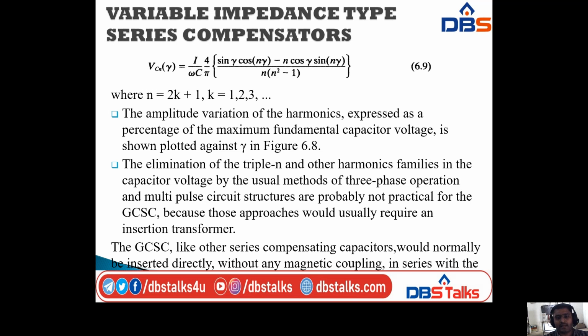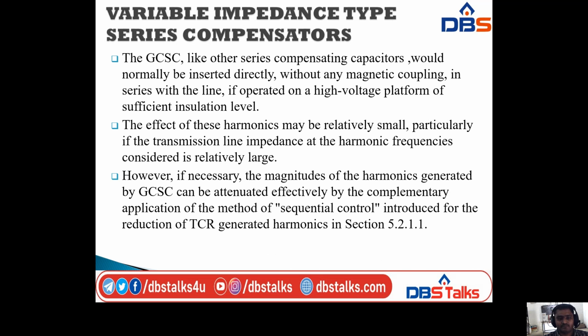The elimination of the triplen harmonic families in the capacitor voltage by the usual methods of three-phase operation and multi-pulse circuit structures is probably not practical for the GCSC, because those approaches would usually require an insertion transformer, and the GCSC, like other series compensating capacitors, would normally be inserted directly without any magnetic coupling, in series with sufficient insulation.